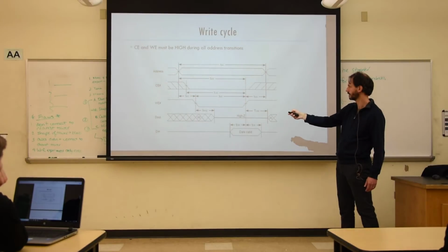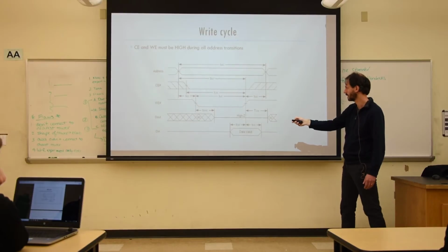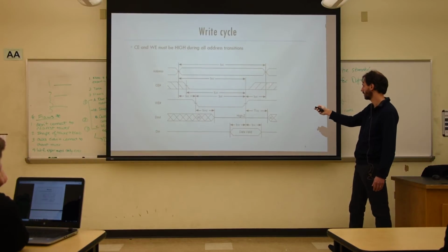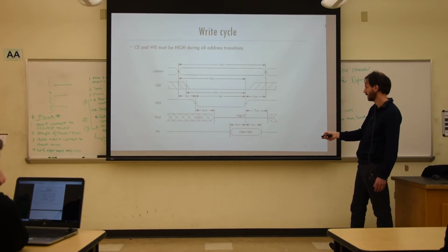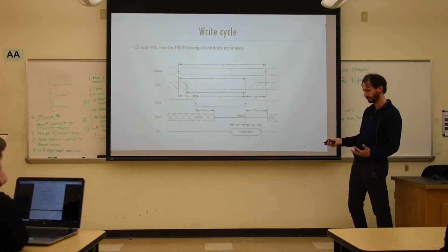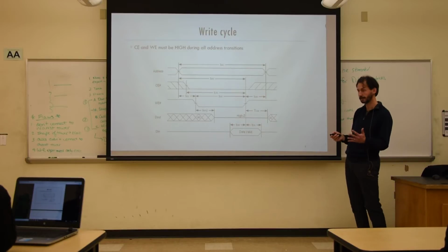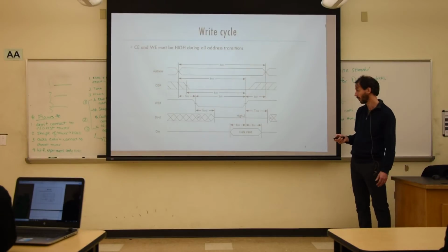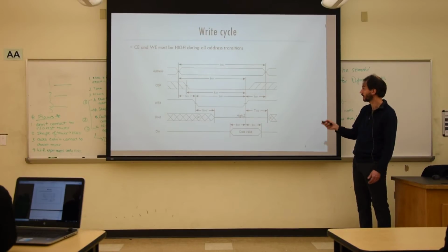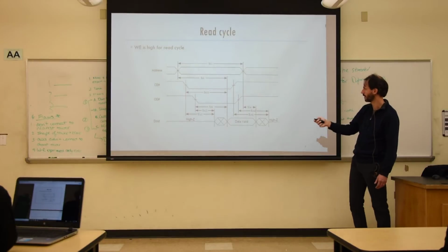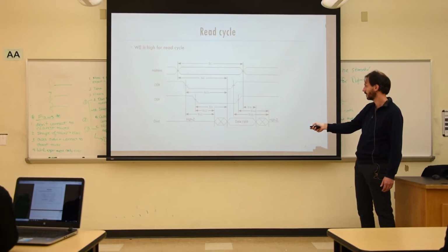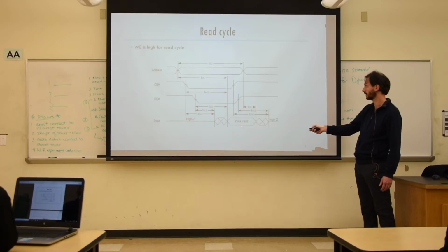So what do you need to do? Well, you need to go through the sequence. So the address information gets on. You need to make this control line go down, then this go down, and this go up, then this goes up. And in the meantime, at the right moments, the data needs to be validly available over those pins that the SRAM expects. If you look at the read cycle, it will be the other way around. Then the data will be coming out and you're ready to actually read it.